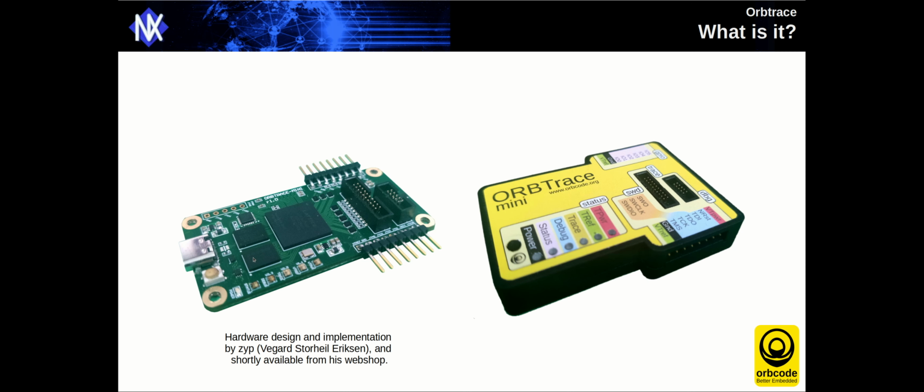We've got 8 megabytes of RAM available, and I think 4 megabytes on the current version of flash for holding the configuration and programs. And this communicates to the outside world over a USB high-speed link. So the nominal speed of the link is 480 megabits per second. We can get around about 400 megabits per second of real-world data out of that flow.